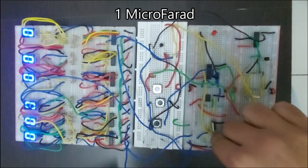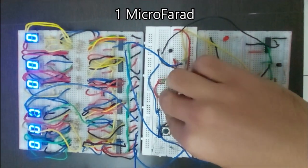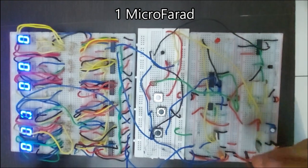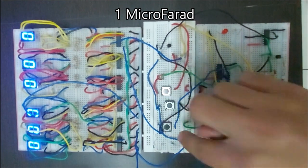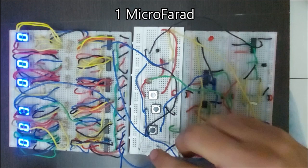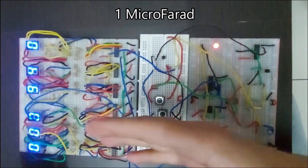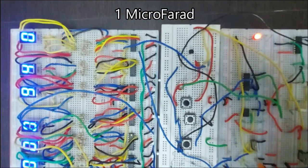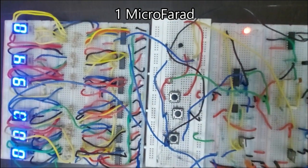Now we are going to reset the circuit. Here we have reset the circuit. Now we just have to test the capacitor by pushing the push button A, and we have to push until the LED glows on. Here we have the value 0.948, which is 0.948 microfarad. That's plus or minus 5% error.